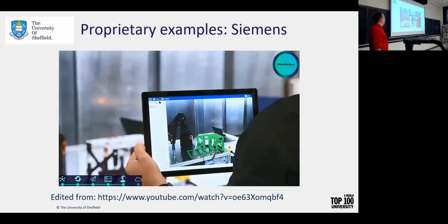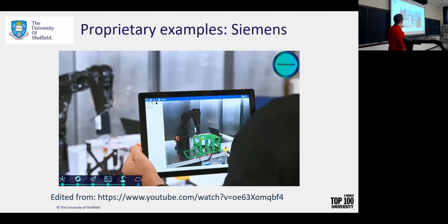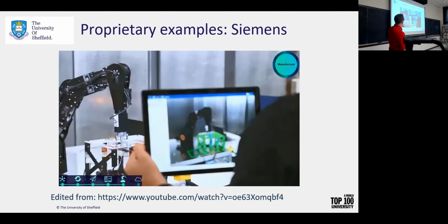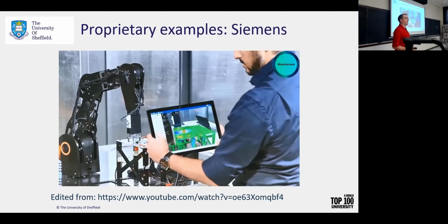I don't know if people online can hear that or not, but we see we have a digital twin of the system on the iPad that's mapping the real world system onto the digital system. So it's using things like computer vision to identify where the robot is, where the actual physical system is, and it's doing on-the-fly computations through a surrogate model. So if I know that I'm going to have some type of pressure being applied to the top of the plate, what it does is it sees and records what the actual pressure is and performs a quick finite element simulation to figure out what the stress distribution is.